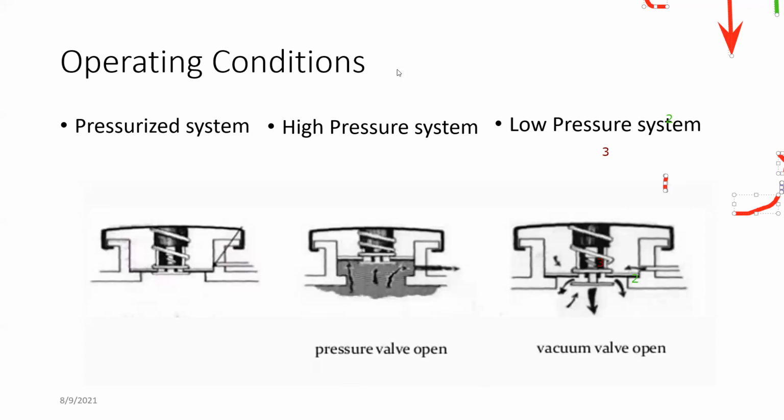so this is your number two and this is your number one, right? Once the pressure increases, this valve will move upwards, the number two valve will move upward. When the number two valve is moving upward, this vacuum valve will not move anywhere because it's still keeping it closed. As a result, this coolant will flow out, reducing the pressure until it comes to the predetermined value.